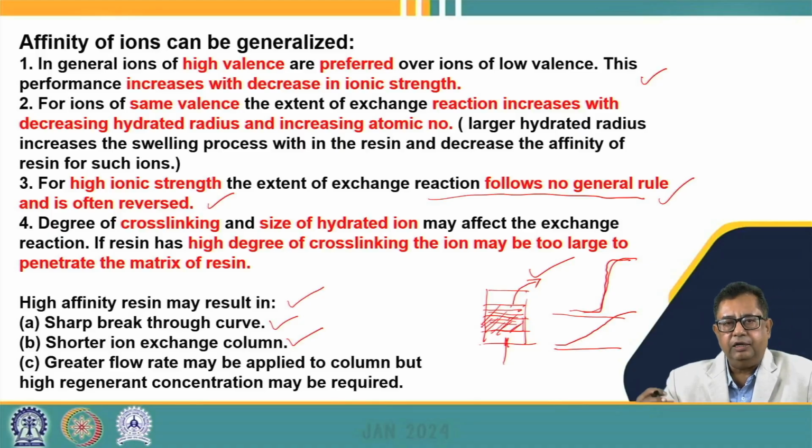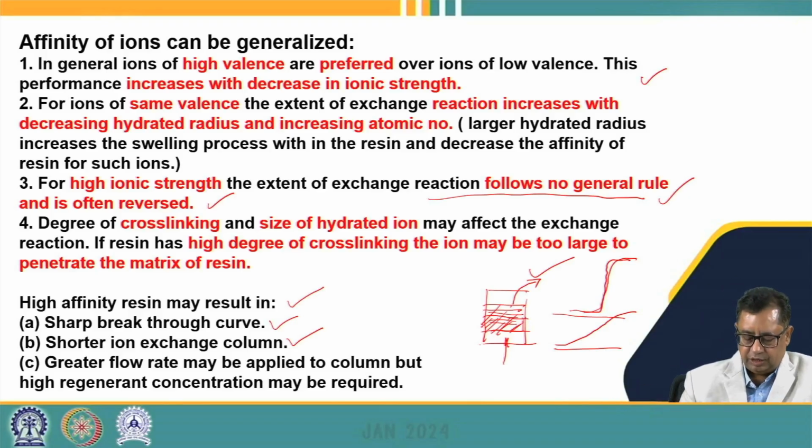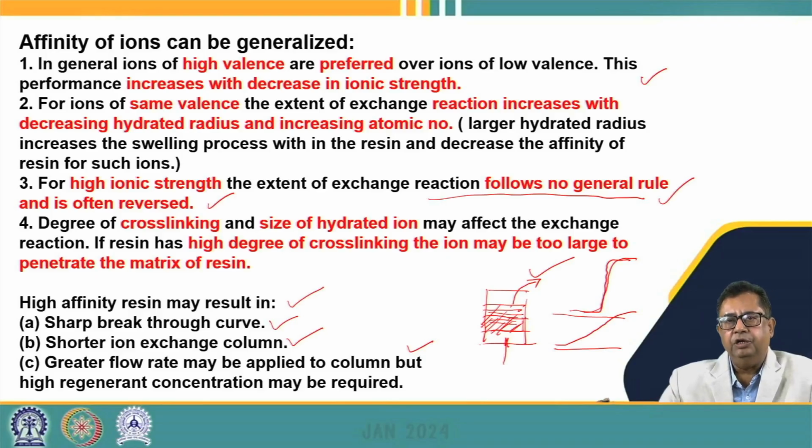So we find that we can use a smaller amount of ion exchange resin in comparison to the weak resins. It may require a shorter depth of the exchange column. Similarly, we can also apply a higher flow rate, because we have a very high affinity towards the ions which are being replaced. That's why we find that higher flow rates may be applied to the column.